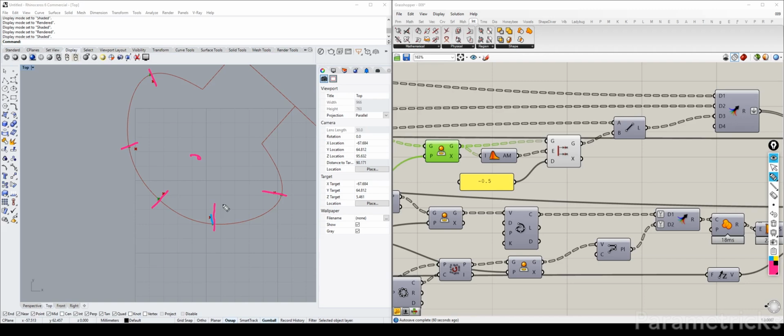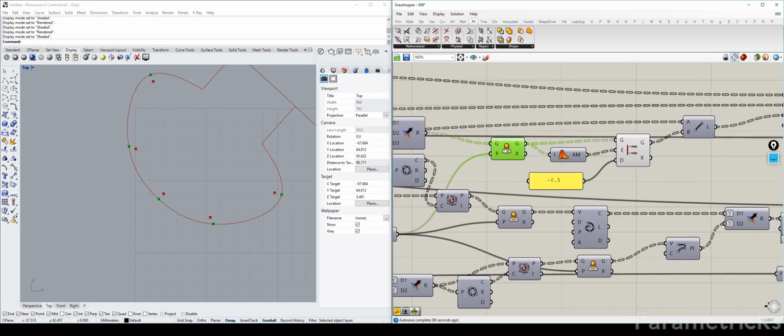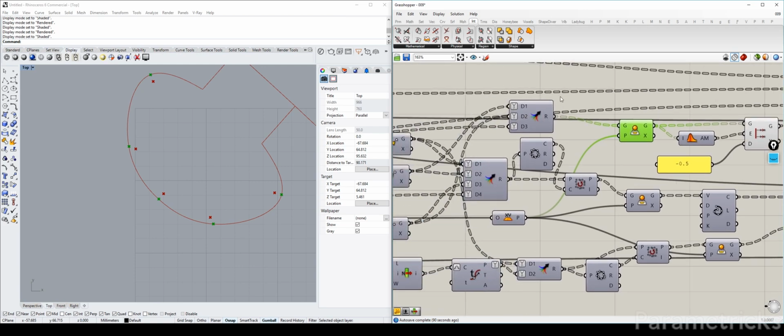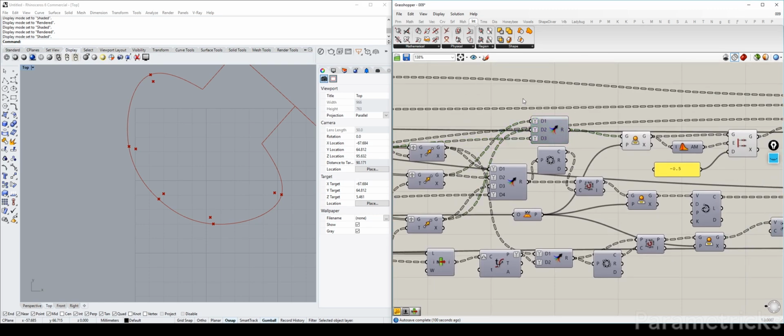But what I'm trying to say is, with the method, if you want to do it precisely, you can have these points do closest point to curve, and therefore you get the parameter on that curve, and then you can say curve evaluation. Therefore, you will get a vector, and using that vector, you can move the points inward. Now, it may sound very troublesome to get all this done, but once you've got it done, it's a one-time investment. You don't have to come back here and move it or change it at all, because you will know the logic that you applied is going to be exactly what you wanted to do. But as I said, I discovered something.